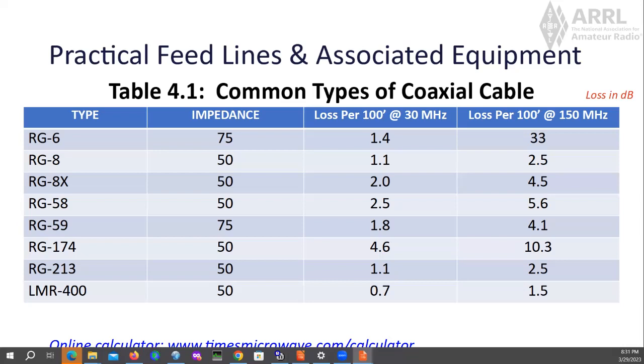That gives you a longer wire. And the practical thing is when you're building an antenna, all of us have a wire shortener. It's called a pair of side cutters or wire cutters. None of us have a wire stretcher. That's why you start out long. But that 468 number incorporates all of those little factors, and it is not a number carved in stone. It is a good guideline.